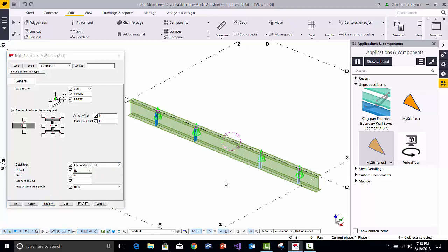And then this will make sure that it's exactly on the side that you had picked when you defined the component. Now, also as a good practice to make sure that that sticks, every time you apply the component by default in the model, if you come in here and type the word standard up here on the save as, that will remember and load that up as a default every time you apply that custom component.